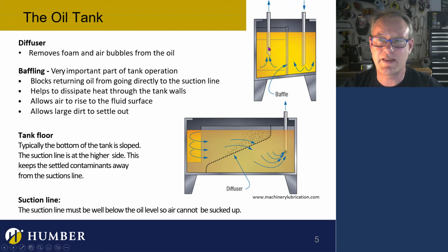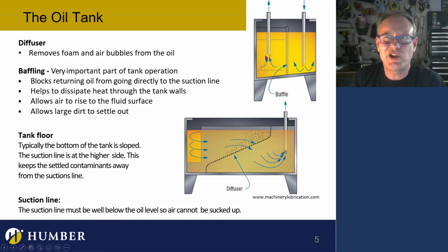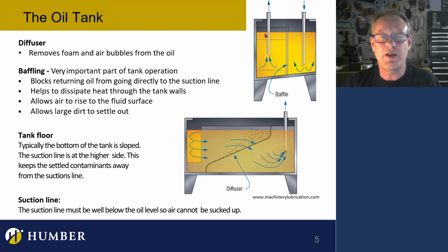But the other is that the inlet or the suction tube has to be not too close to the bottom, but also not so far up that it's going to be sucking up air. So it's got to be in the middle. It has to be absolutely below the fluid level. So we've seen in both cases, the tube has to be below the fluid level.